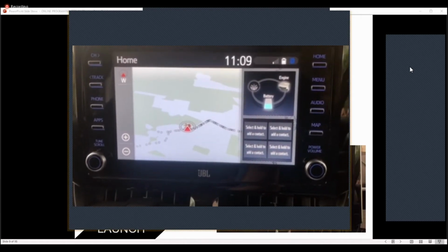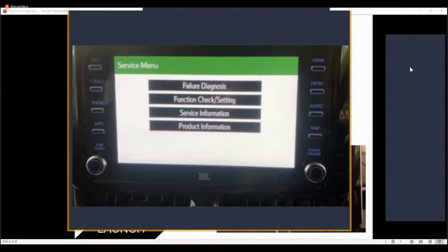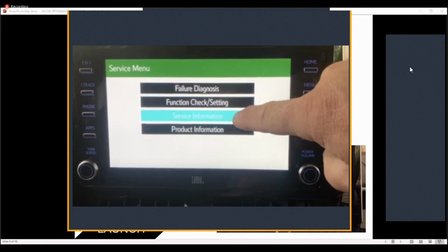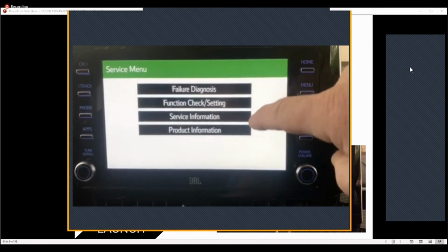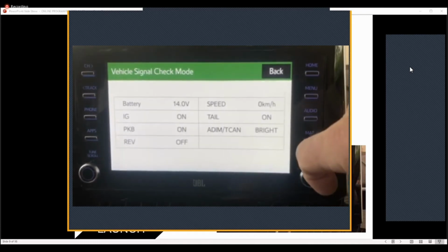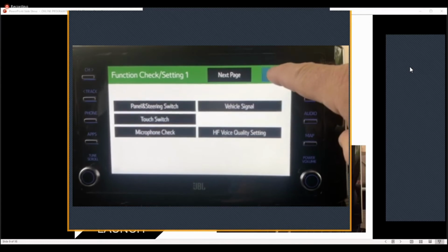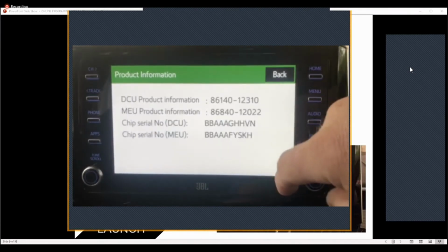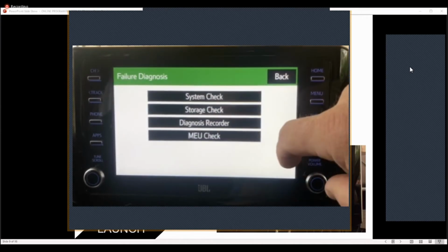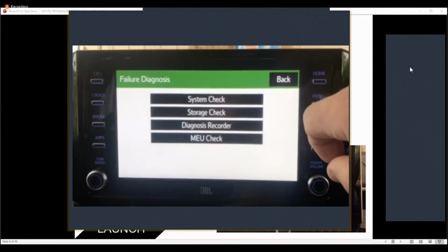So this is where the navigational system, once the scan tool sends that command, turns it into the service mode. So now the actual diagnostics and the information are not on the scan tool, but actually on the vehicle itself. But you need the scan tool to go into this mode. So this just gives you an example of what some of the special functions are actually doing.